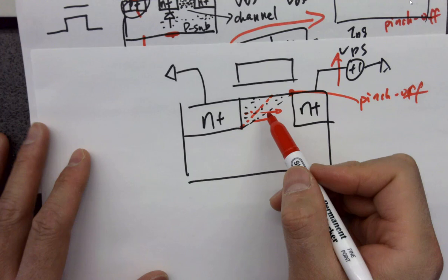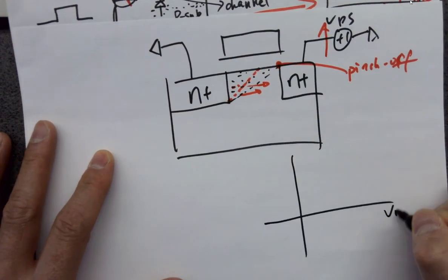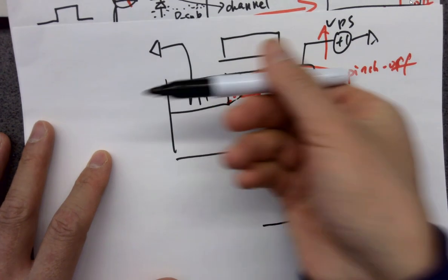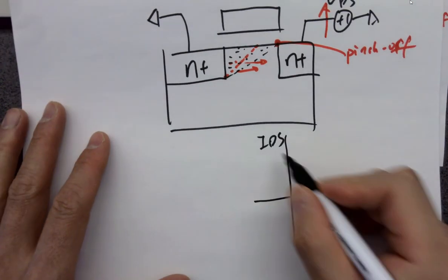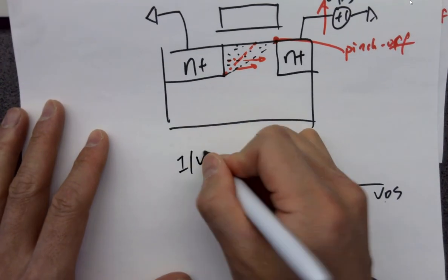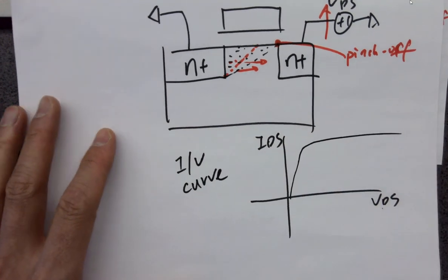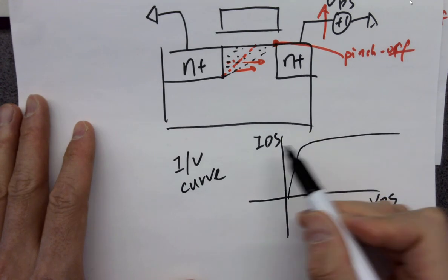It's almost saturated. So the curve looks like this, ideally. Okay, VDS, IDS. IDS is current going that way, which is electrons going this way. It's called VDS versus IDS. It's one of the IV curves we care about. It's going to be on the quiz. So it looks like this, ideally, and this should be flat. But in real life, it's not flat.